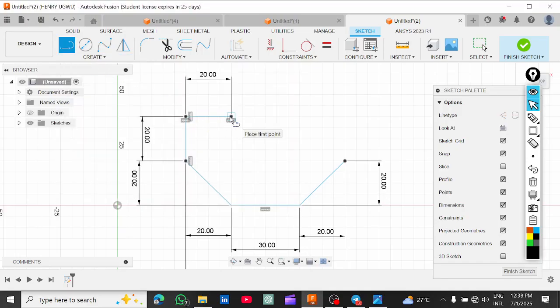Okay, so I will place my line tool mouse here at this point. Let's click on it to activate the line, and I'll scroll down. Before I click on the second line, I'm going to add my value, which is 15 millimeter. If I click on that second line, you can see it adjust. So you can adjust the dimension on your line tool or any of the tools you are using before you conclude that operation.